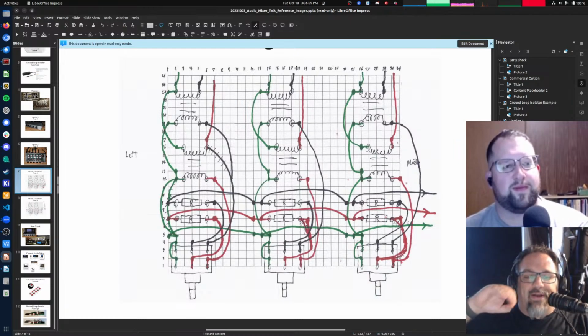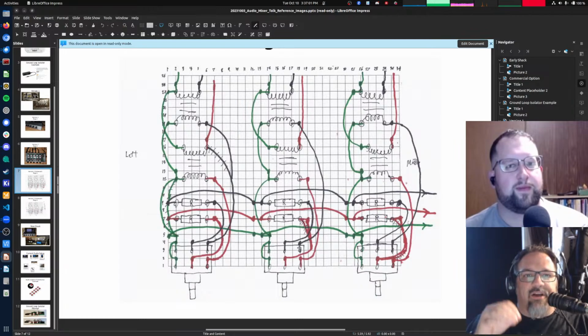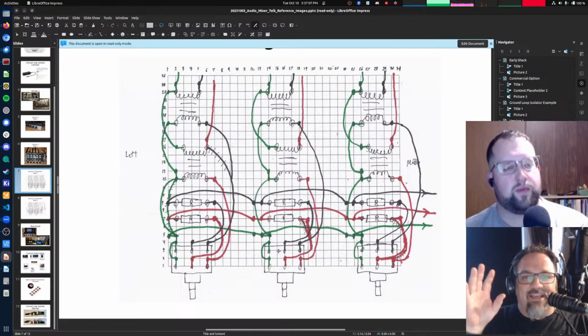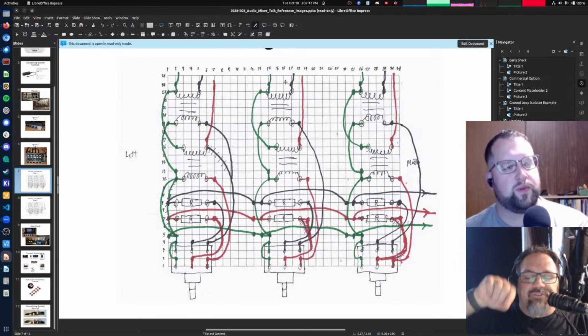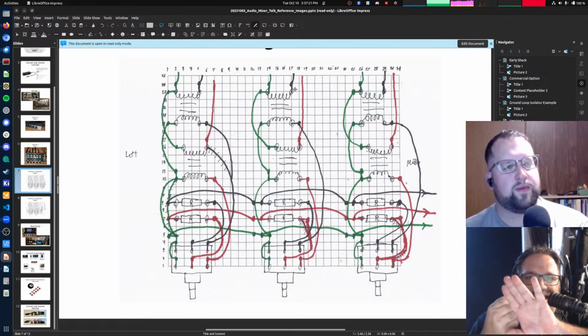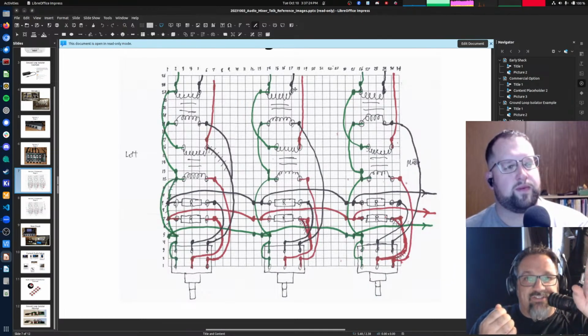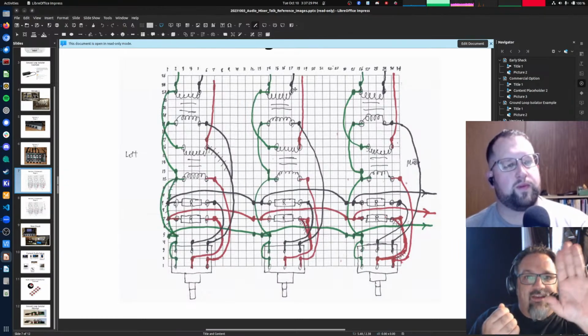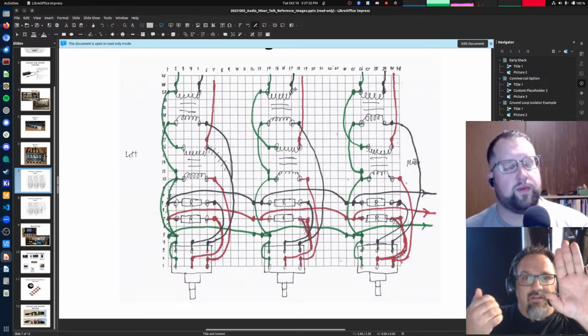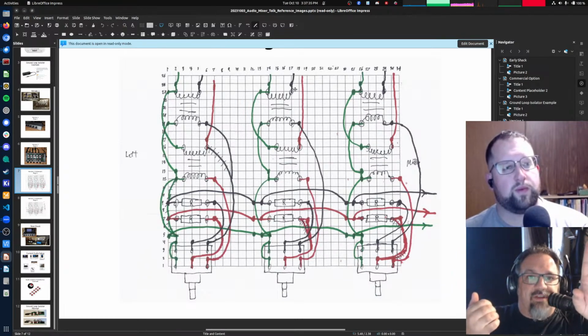So you've got power because none of this is 0 ohms to ground, right? It's a pretty high impedance signal because it has to go through all of these resistances. But you do have a signal through some impedance into the input of your Flex. And if the active audio amplifier in your Flex is turned off, it's not driving the output to anything. So it's going to be a relatively high impedance, because an unpowered transistor looks like a high impedance.